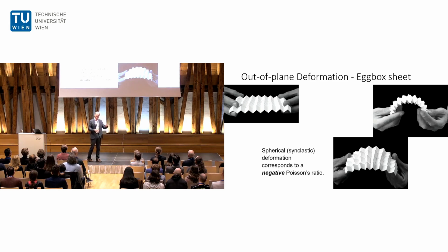So we have this very odd situation, at least it seemed odd to me, that you have a material that you've made, a sort of metamaterial, by taking an origami sheet and folding it in one way, or taking a sheet and arranging it for the egg box pattern. Each of them then have some emerging properties as a metamaterial. And those emerging properties are not the properties that you would ever get with a single standard material, because you have this reversal in effect of what the Poisson's ratio looks like.